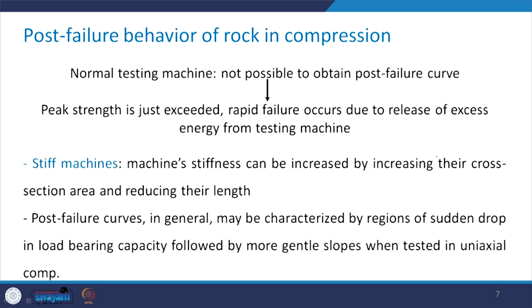Now I mentioned to you in one of the earlier classes that the post failure behavior of the rock in compression is important in order to see how it is going to behave in the field, or what is going to be the strength after it has achieved the peak strength. As far as the normal testing machine is concerned, it is really not possible to obtain the post failure curve using such machines.